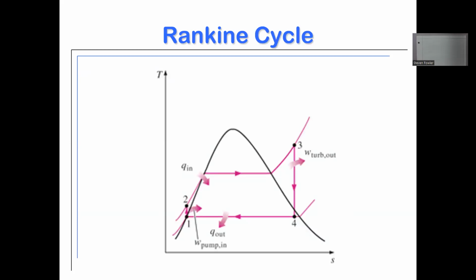Graphically, remember, because we're dealing with water in an engine or some sort of refrigerant in a refrigeration cycle, we've got to work our way around the saturation zone on a T-S or a P-V diagram. You can see these are lines of constant pressure going across here, and we follow a long line of constant pressure to go from 2 up to 3. Then we follow a line of constant pressure going back from 4 to 1, right back to the point of saturated liquid.